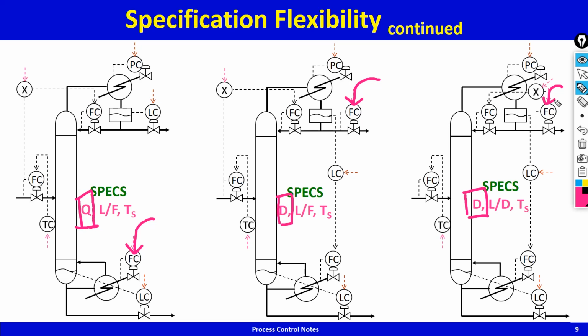That means there exists no steady state for this set of specifications. Or like in the previous case I was talking about, under specifying. You think that you're specifying, but there is actually a material balance relationship between those variables, so that's actually under specifying, and therefore you get infinite solutions. The recycle tier will settle wherever you guess it. So these are all issues that are there, and I hope these issues are clear.